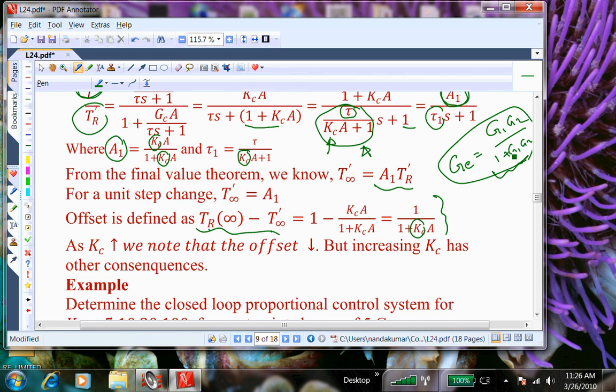Here I have an effective transfer function. It's a single input, single output system. You're going to generalize this to multi-input, multi-output, then you'll get a matrix, then you'll get the eigenvalue of the matrix. Here, all I have is a single input and a single output, okay? And I have an effective transfer function that contains the action of the controller KC in it. So as I change KC, the dynamics can change, can become unstable.